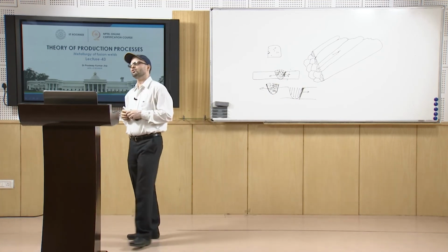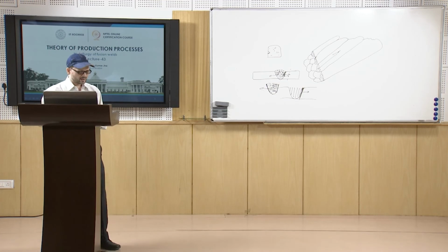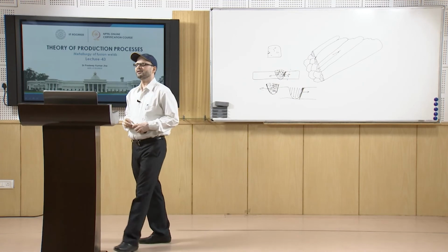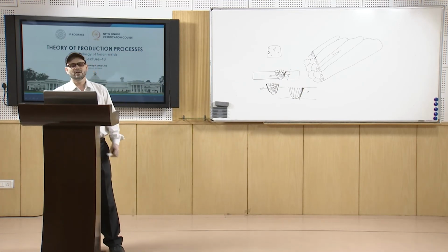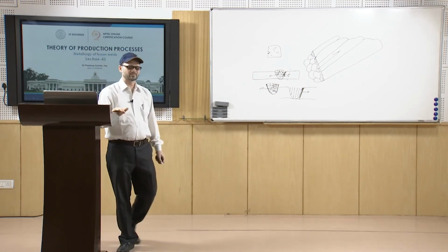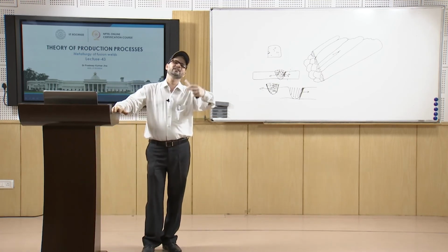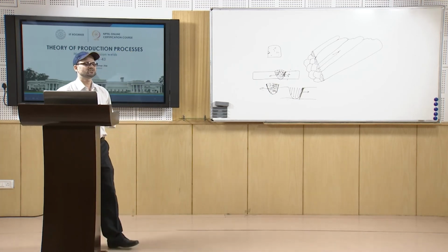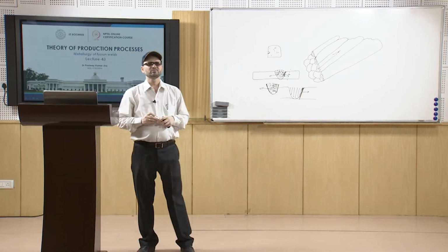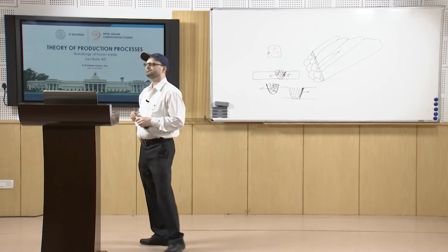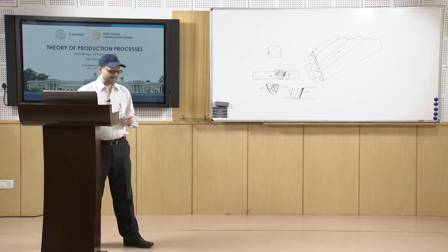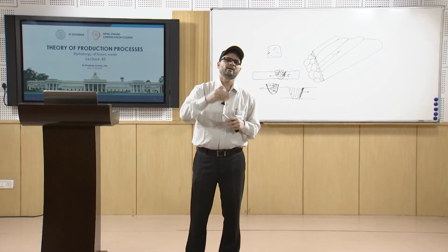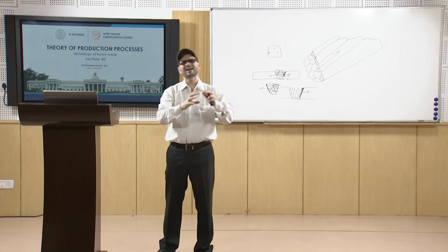In this case there is normally not much structural change, but there may be certain effects of heating and residual stresses, and dynamic strain aging is normally seen in such cases, which makes the phases brittle in many senses. That is the trait of the zone of unaffected base material.